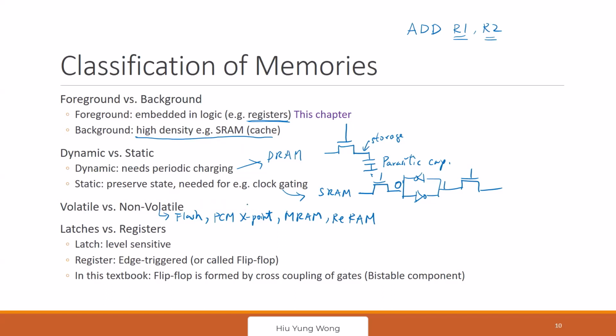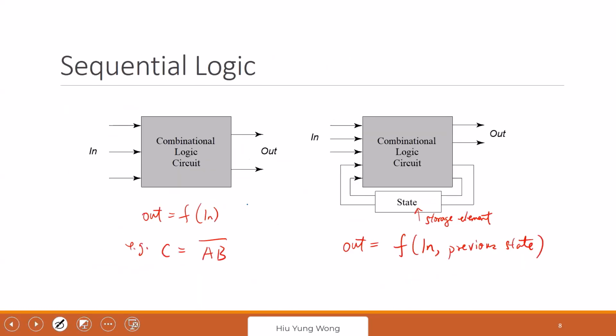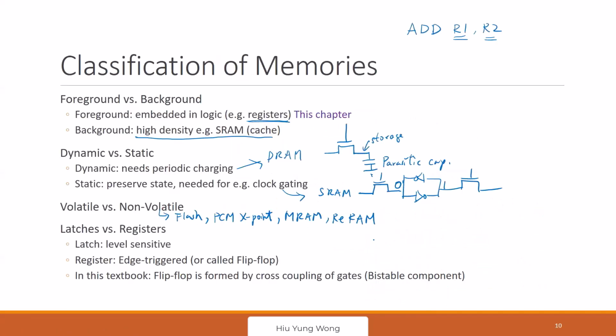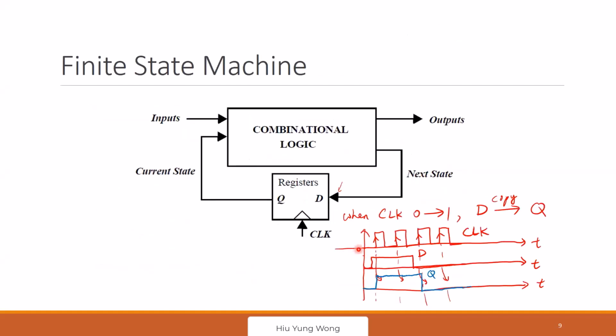But the last thing I want to talk about is the difference between the latch and register. Okay, what is a latch? Now that relates to what Sai just asked me, right? This one only copies when it goes up. Some memory will copy whenever it reaches a certain level. Not going up. It's not about the transition. So it's called level sensitive. I will explain more. Another is edge trigger, like what we're doing here. It copies when it changes state.